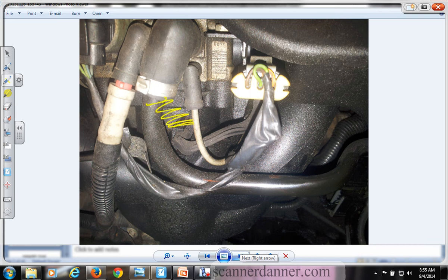Vacuum levels in the intake would be changing rapidly, but we would be trapping vacuum up at the MAP sensor. Does that make sense then that during a decel, when I should have this reaction of a very high vacuum, that we have some trapped stored vacuum in the MAP sensor itself? It should. This is what's going on with this car. It wasn't just a decel problem though, wouldn't you agree? As you try to accelerate, what should be changing very rapidly at the MAP sensor? If you accelerate and we drop manifold pressure, shouldn't that same drop in pressure also come up to the MAP sensor and tell the computer we have a higher load condition taking place? What's the computer's reaction?